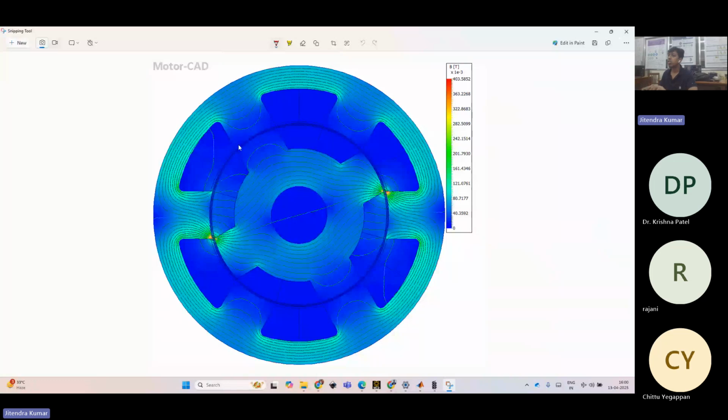So see, this rotor tooth width, when it is equal to the stator tooth, then only the entire stator tooth will be in the aligned position, right? And beta r plus beta s is not always equal to the slot pitch. Let's suppose this position.